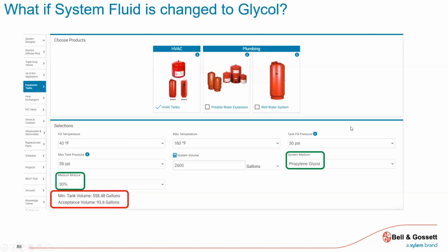Maybe Will can speak to that a little better, but the diaphragms are typically in a smaller water volume, smaller expansion, and less expensive, technically, ASME versus going to bladder. But you get to a certain volume size tank, economically, it just makes more sense to go to the bladder at that point. But it's system volume, typically. What's the total expansion? So on the smaller sizes, smaller systems, you'll typically see a D style, a diaphragm ASME. And then when you get into that larger volume, like 2,600 gallons, it might make more sense to be moving to the bladder.